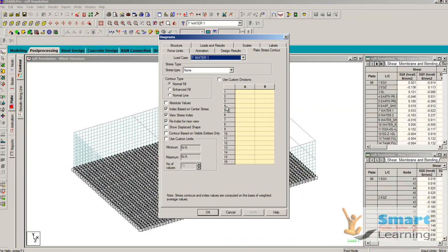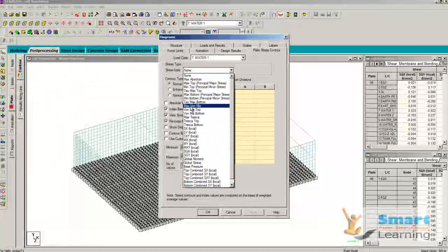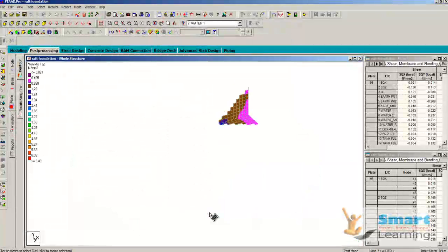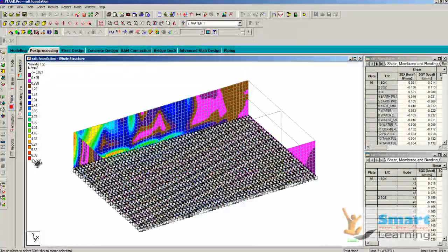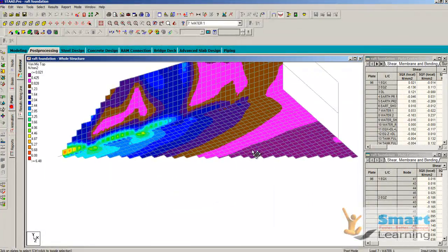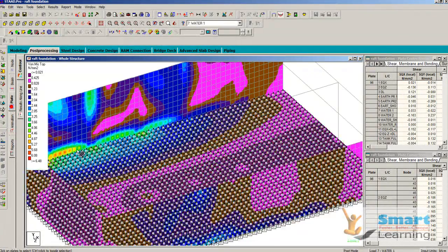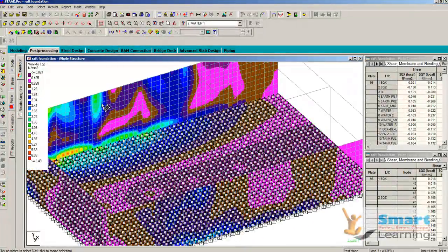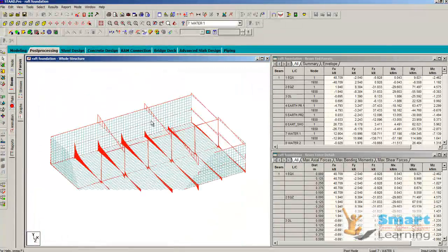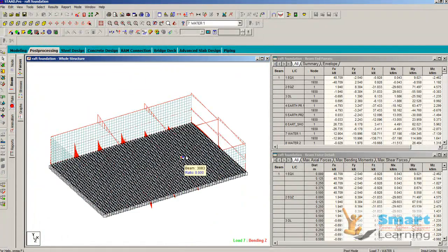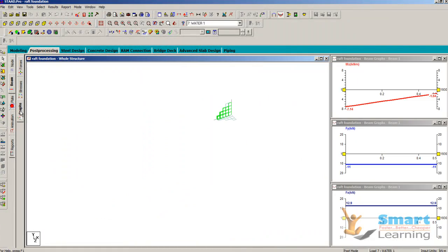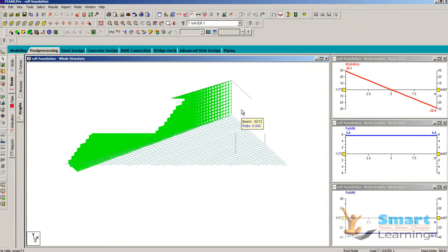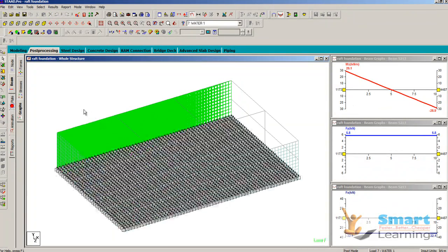If you go to the plate, the plate von Mises stress top will be computed, and here you can see this is reliable and has a very good response, and which area has which stress distribution. Here you can see the maximum stress at this corner, and if you go to the beams, over these beams also you can see the shear force and bending diagrams, and you can go to the graph and independently follow and see the safety.